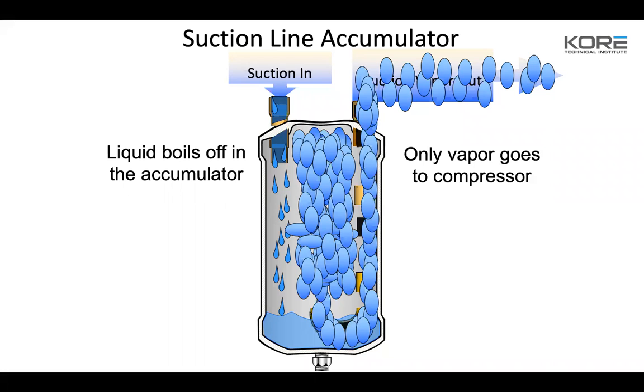Correct. Yep. And so that's what I'm saying, guys, is once you get it to optimal temperature, what you should see is frost at the bottom, and then it should start boiling up about a third to midway up. If you're getting more excessive than that, then when it gets colder or when the ice doesn't melt off that thing, all you're going to do is knock the oil out of that compressor and then try to compress liquid and take the valves out. So what you really want to do is that's how you determine if the accumulator is sized correctly.